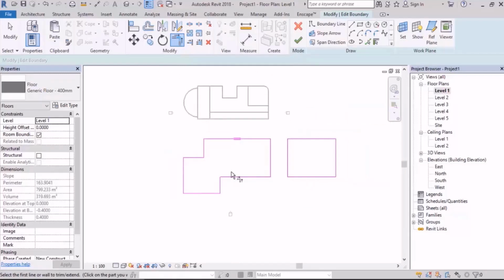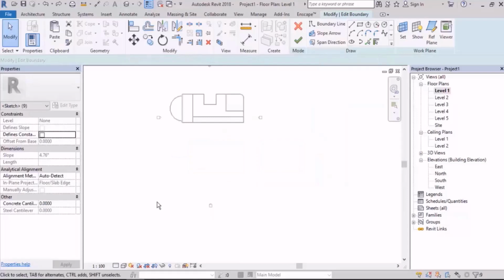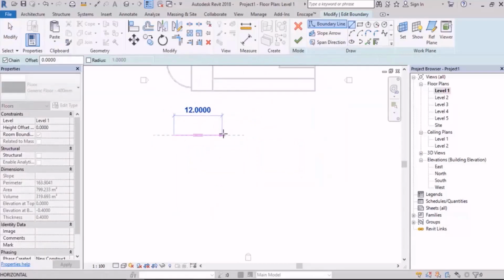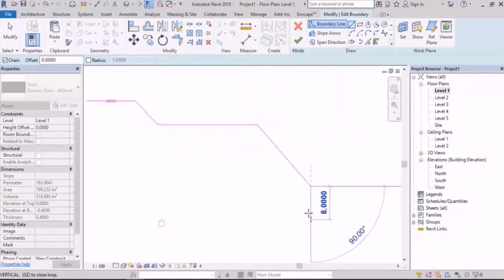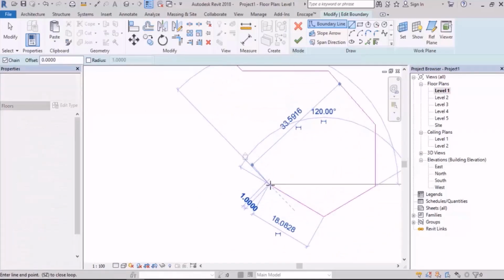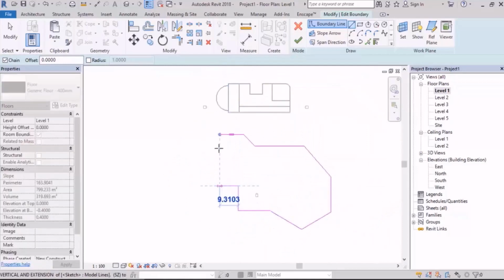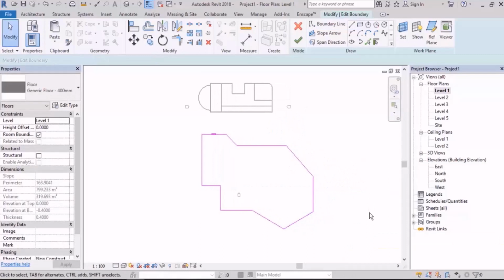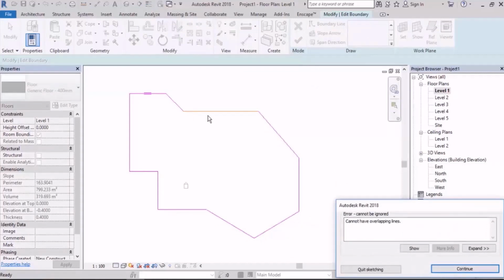Okay? So the next problem is sticking some shapes together, which is wrong. But the third one, which I think is the most important, and it's also a bit difficult to find, is the overlap error. When you have very big projects, these things happen to you a lot. A lot of overlaps are made in the project. Let me draw it. Let me also make a space here and tell you how it's solved. Like this, and one extra on this one. Don't just rely on the highlight, many times you don't see it at all. Now it's something that seems so perfect, but when I click on finish, it tells me that I have an overlap, and it shows some orange lines too.